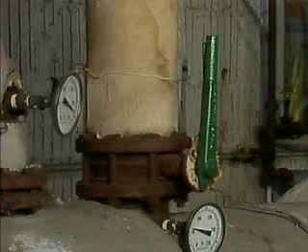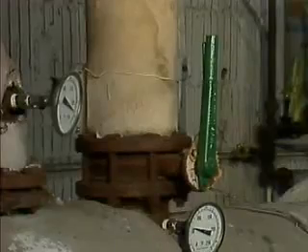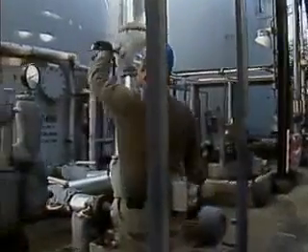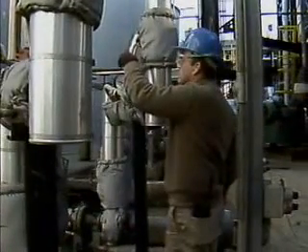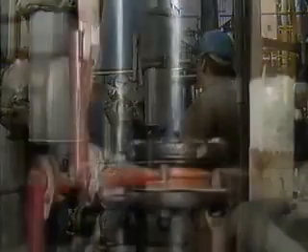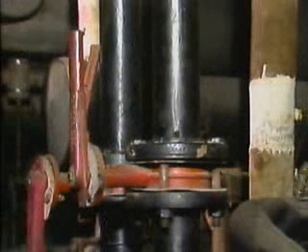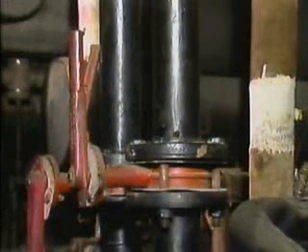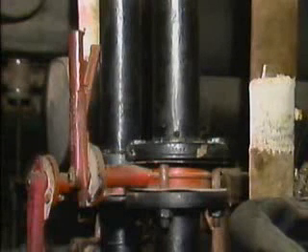The rate of fluid flow through a butterfly valve is adjusted by using the handle to change the angle of the disc. The handle is a lever that may include a spring-loaded locking device. To change the position of the valve's disc, compress the lever and turn the disc to the desired position. A lever with a locking device is frequently used as the handle on a butterfly valve because flow through the valve can sometimes cause the disc to flutter or change positions. Locking the lever in place helps the disc resist the force of the fluid flow and stay in the proper position.